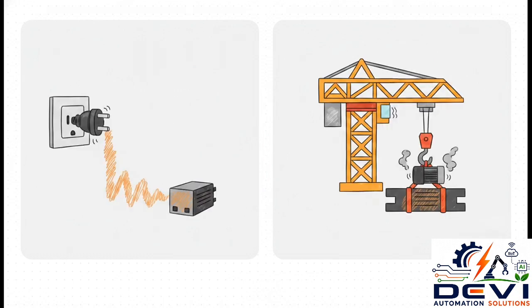Next up, we have undervoltage and motor overload. These are great because they point you in opposite directions. Undervoltage, or UV, points backward to your power source. It tells you there's a low supply voltage, maybe a loose connection, a general power failure, or some issue back at the MCC, the Motor Control Center panel. Motor overload, or OL, on the other hand, points forward to the mechanics. It triggers when you've got a consistently high load, a mechanical jam, bad bearings that are adding friction, wrong motor parameters in the drive, or a serious cooling problem happening in the motor itself.